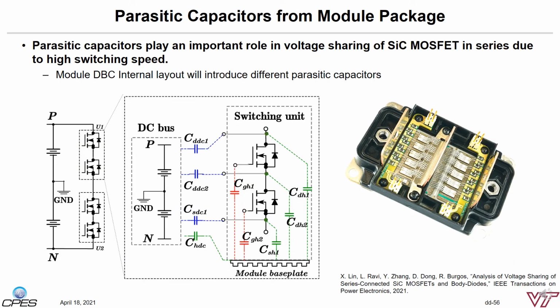The most critical design consideration of devices in series is the voltage sharing, especially the dynamic voltage sharing during the turn-off process. The good news of putting silicon carbide MOSFET in series compared with IGBT or IGCT is that the MOSFET is a unipolar device, so the device turn-off process is fast and consistent. The gate voltage control can precisely control the device turn-off process. Therefore, we can reduce the snubber component size a lot, compared with IGBT and IGCT, of which the turn-off process involves two types of carriers and also is slow and not consistent.